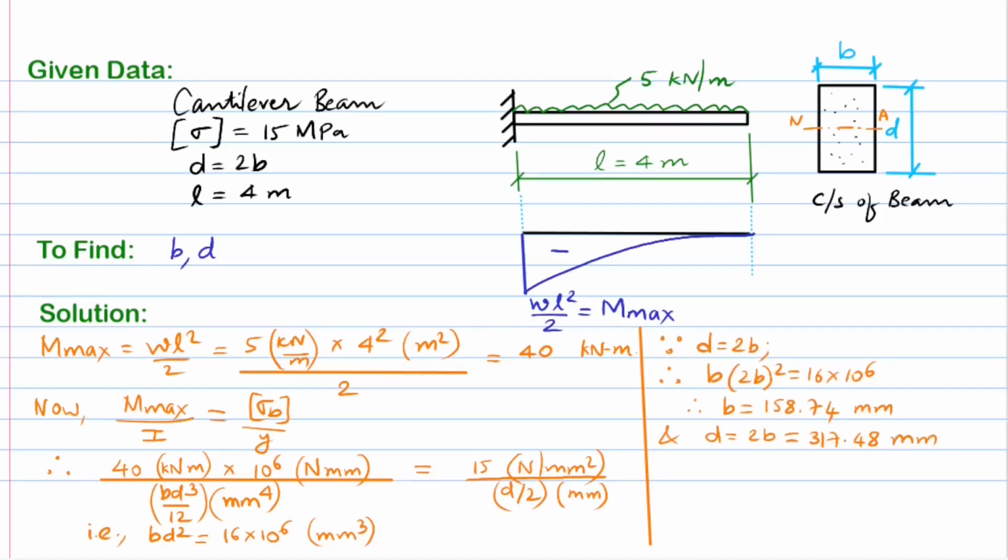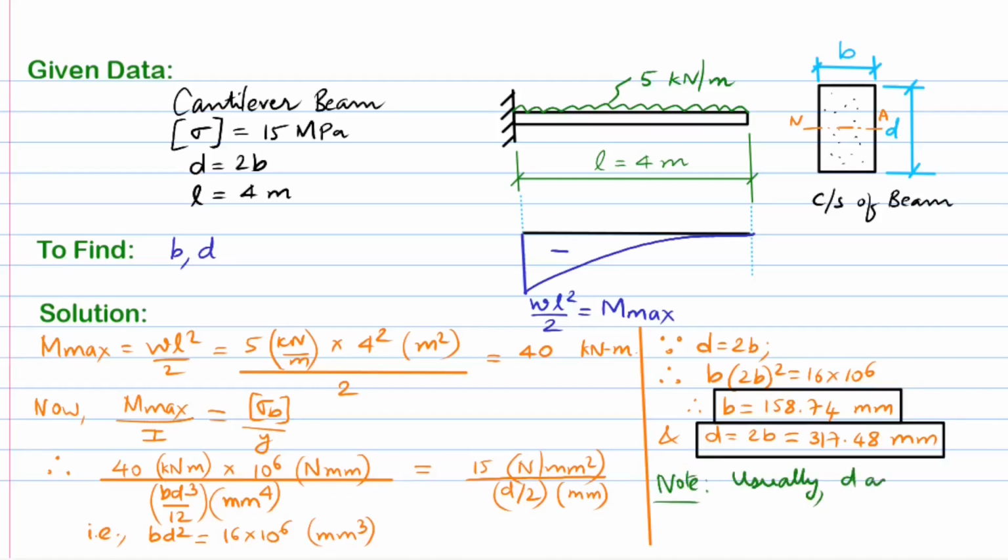It's worth again noting that these sizes in decimals are normally not used in actual practice as beam cross-section dimensions. To take into account the standardization and interchangeability concepts, these are usually rounded up to the next available cross-section dimensions as per the available standards.